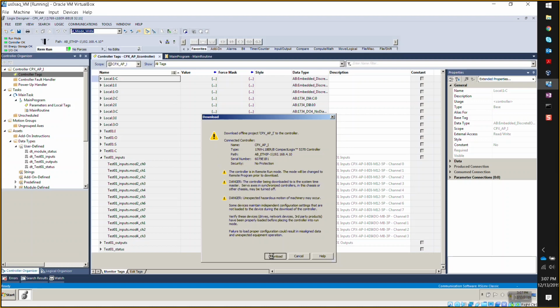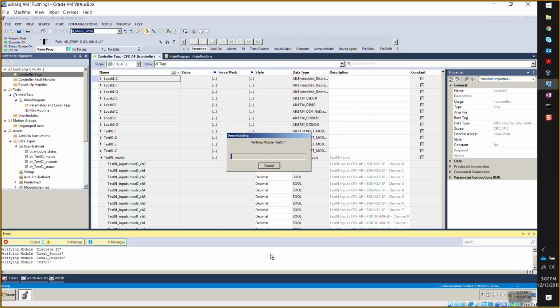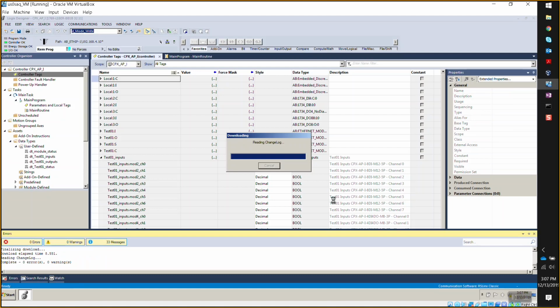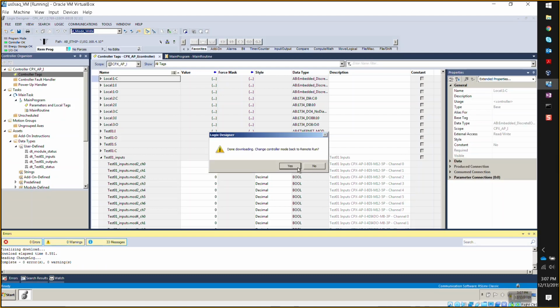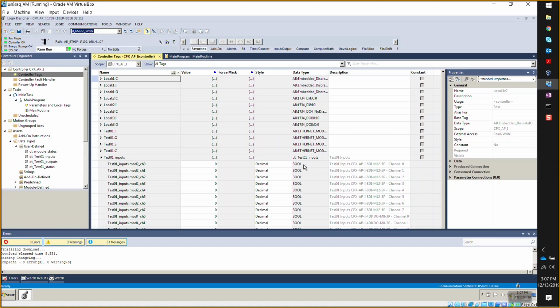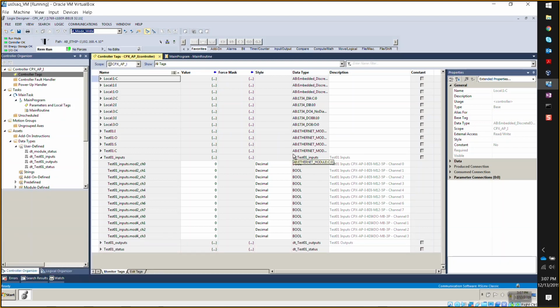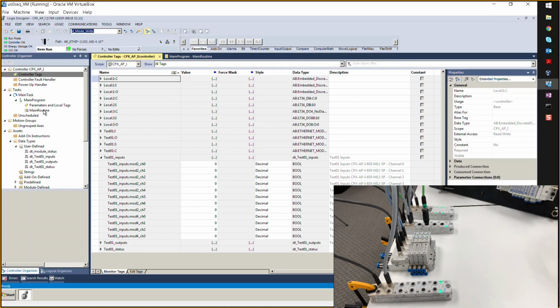So to me, it seems like the cleanest and most elegant way of doing it is with the L5X, because that way it brings all of the diagnostics. It also brings all of the tags, which is really important. Yes. This to me seems like the most elegant way, and it's actually pretty quick in a way. I mean, yes, I do have to go through the process of exporting and importing and all of that, but at the end of the day, it gives me a lot of additional functionality. Absolutely, I agree 100%.